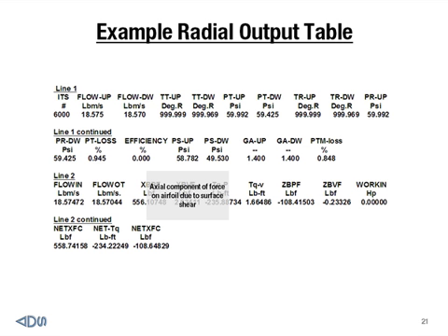Those are typically relatively small. The pressure forces are typically the dominant forces. Next are torque forces on the airfoils. They could be used to size the attachment fasteners or for shaft torque reasons, sizing the shaft. And then due to airfoil shear, again, the shear forces are small, but because this is a full 3D calculation, we're able to get that level of detail.